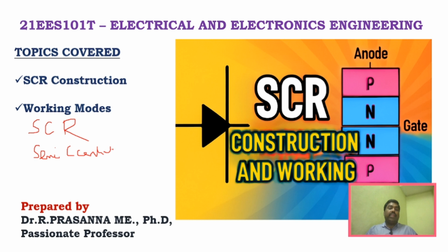Semiconductor controlled rectifier. When we say semiconductor, it can be silicon or germanium, but mostly silicon is preferred for SCR construction. That's because silicon has very low leakage current. That is why silicon is preferred mostly, and that is why it is also called a silicon controlled rectifier. But actually, it is semiconductor controlled rectifier, right? So now we will see the construction of SCR.